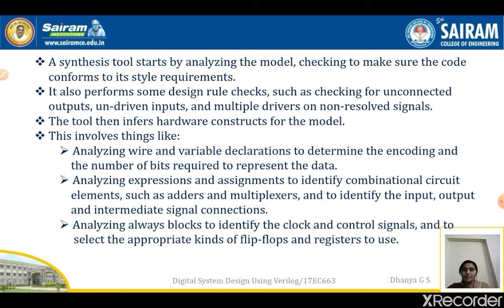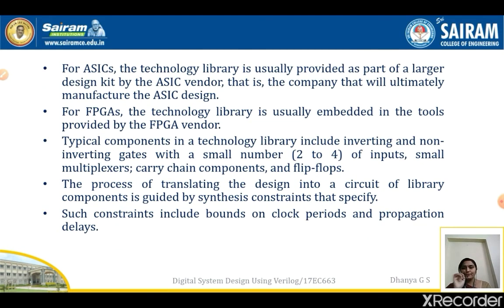Then it analyzes expressions and assignments to identify combinational circuit elements such as adders, multiplexers, etc., and to identify the input, output, and intermediate signal connections. Also it analyzes blocks to identify the clock and control signals and to select the appropriate kind of flip-flops and registers which have to be used.